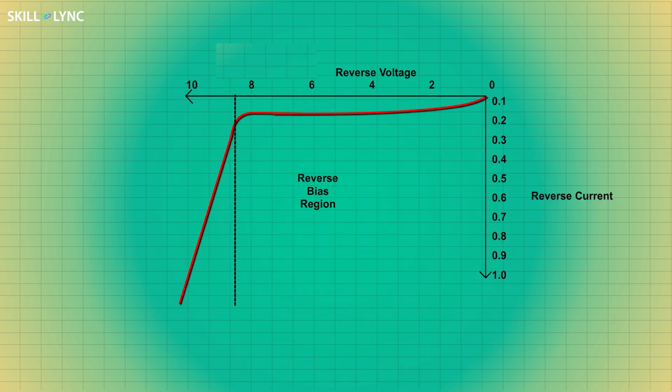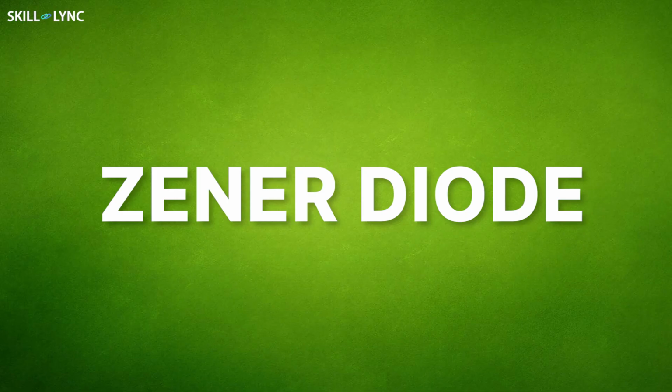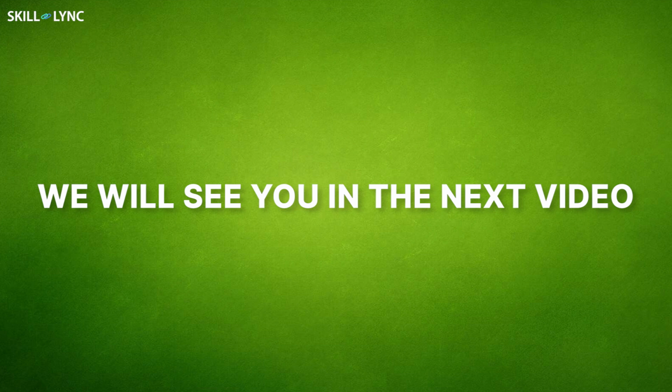However, the magnitude of the current is in the order of microamperes. If we continue to increase the reverse bias voltage, it will lead the diode to overheat and break. In order to prevent that, we use the ZENER diode. We'll learn more about the ZENER diode in our next video. In this video, we learned about the different biasing modes of a PN junction diode.